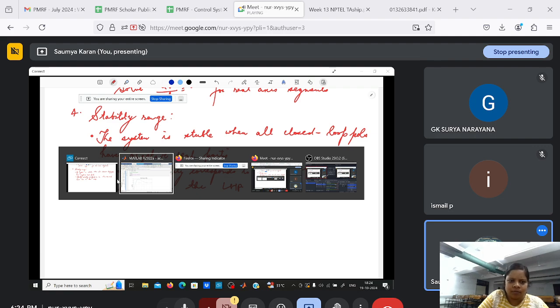So this is a very simple way in which we have written the transfer function to be equal to 1 upon s into s plus 2 into s plus 5. Root locus can directly be plotted, rlocus G. Okay. Title, root locus of G(s)H(s) of the same transfer function. Let me run this.